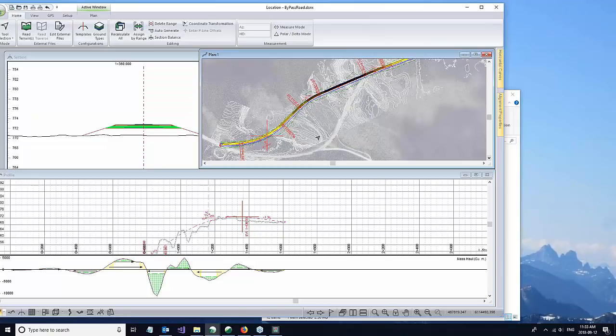Whereas if you have a fixed horizontal alignment and you optimize vertically, you will get the best vertical subject to your terms and conditions for that horizontal alignment. The horizontal alignment optimization is really more of a, let me see if I can find something better tool. Let me go look for something better, and I'll tell you about it when I find it. But to answer your question, yes, it deals with both horizontal and vertical simultaneously.